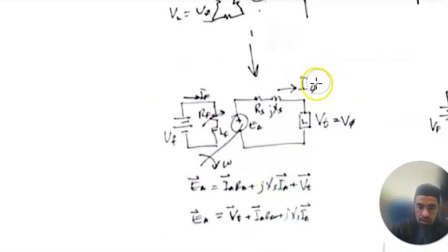So draw your equivalent circuit for your generator. Generator means it converts the mechanical rotation of your shaft into electrical output current to your external load and external lines. You have V field to provide the magnetic field to your rotor.